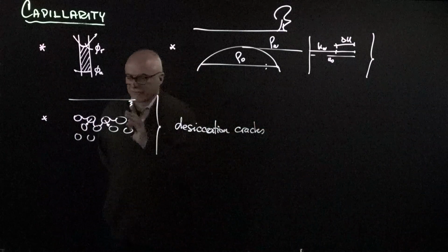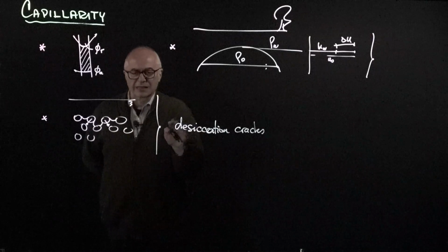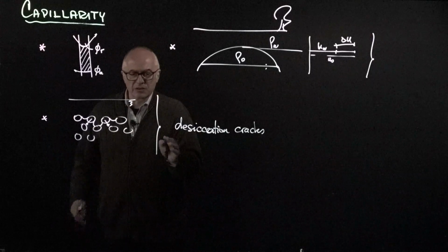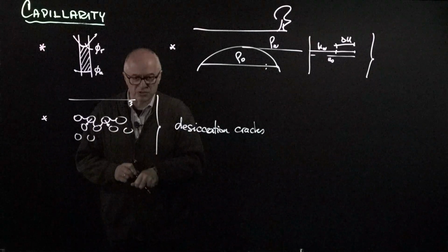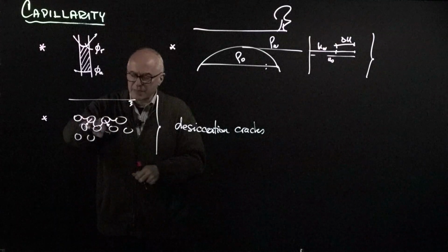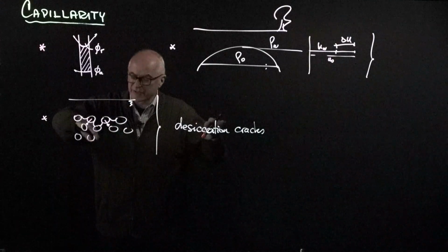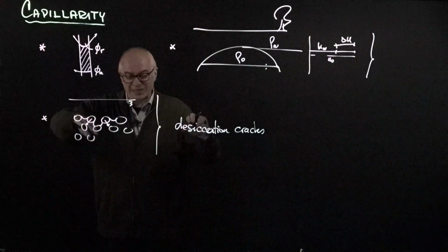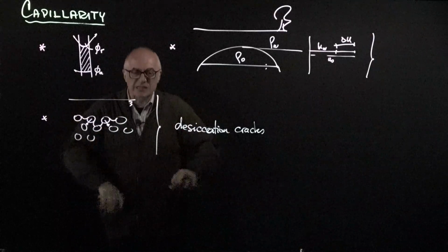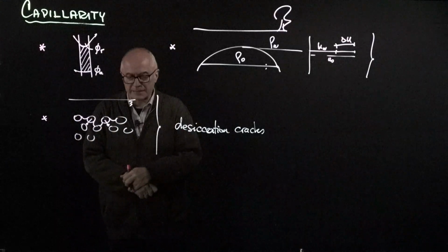And this is the fundamental. There is no tension capacity in the soil. It's all about the preferential water invasion and the invasion of the capillary meniscus, the surface interface, the interface between air and water, and how that causes the displacements of the grains.